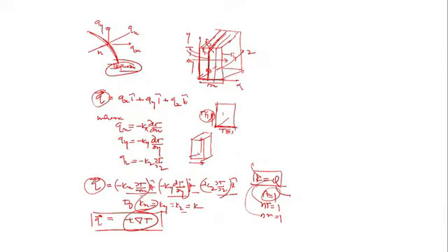In the x direction the ability to conduct heat is different, in the y direction it is different, and in the z direction it is different. That's why kx, ky and kz. In the same material, the thermal conductivity may vary, and that type of material is called anisotropic material.